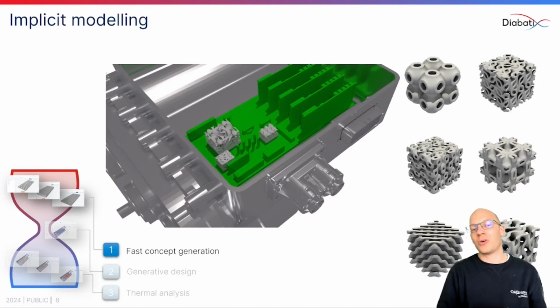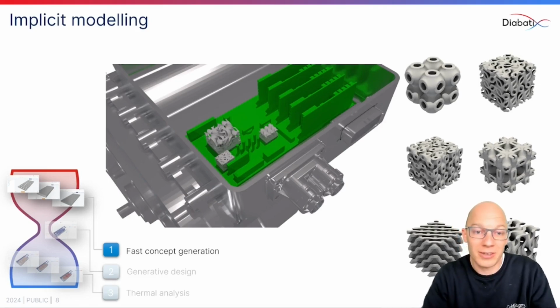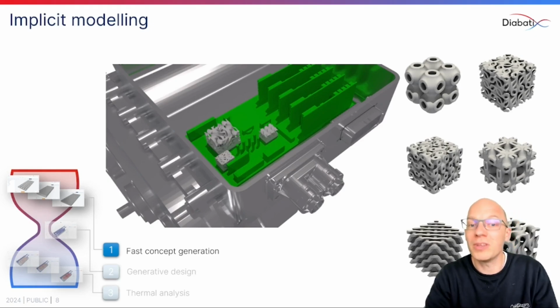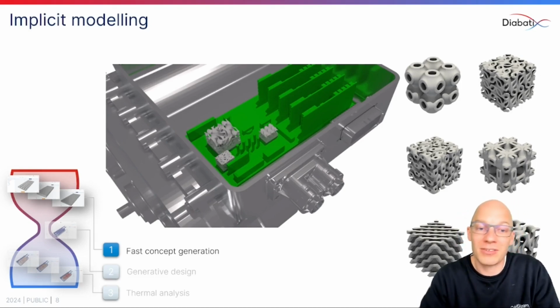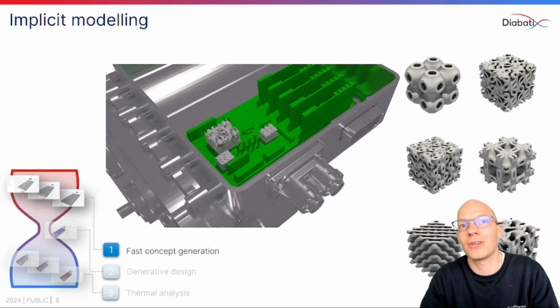So we extended our library of shapes that are evaluated quite significantly from considering only pins and fins to a wide range of shapes, going into the 3D printed section with these implicit models, gyroids, linoids, and so on. All have become available to you. But as well, we extend quite extensively on the pins, the fins, the diamond shapes, and so on, combine them with all the ranges of manufacturability constraints you can set to make sure that not a single option has been left untouched.